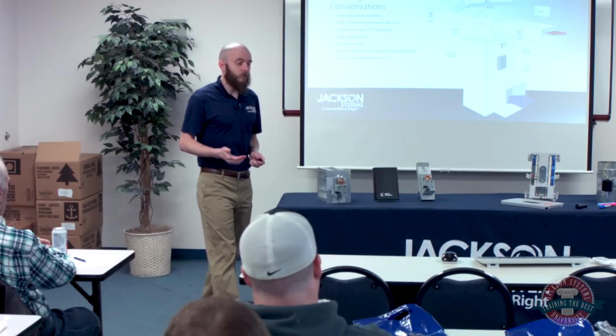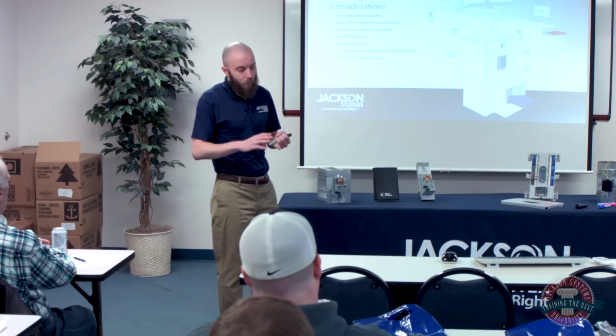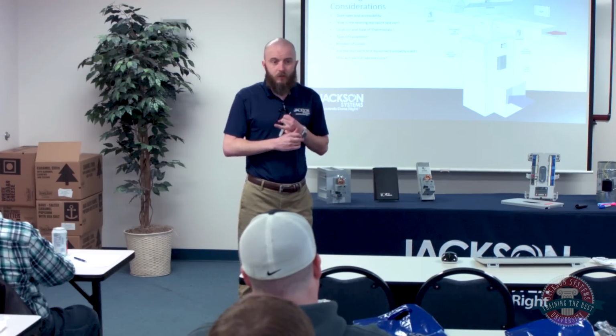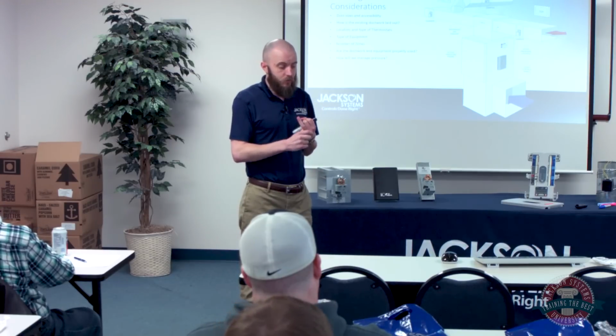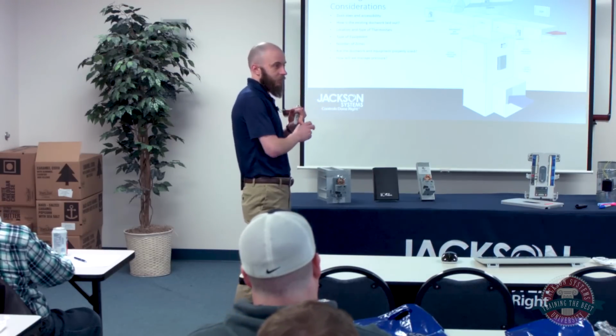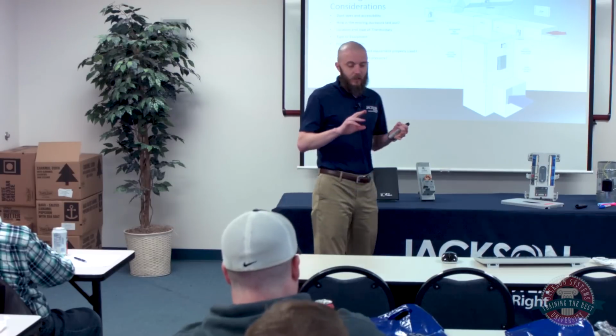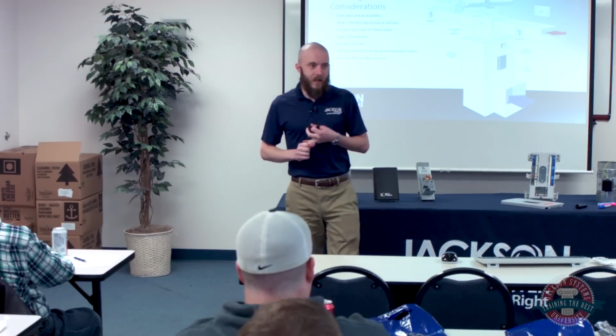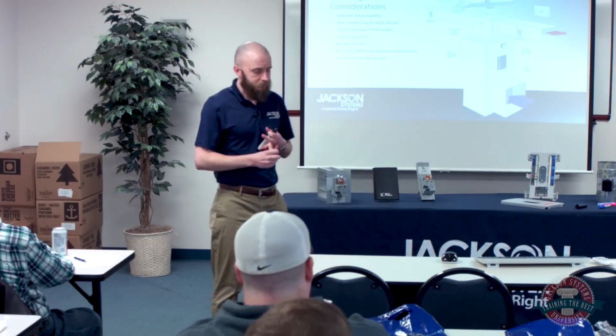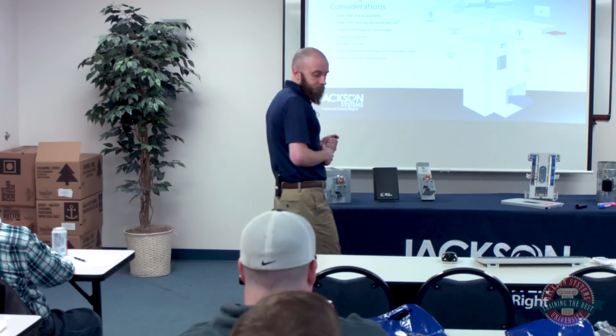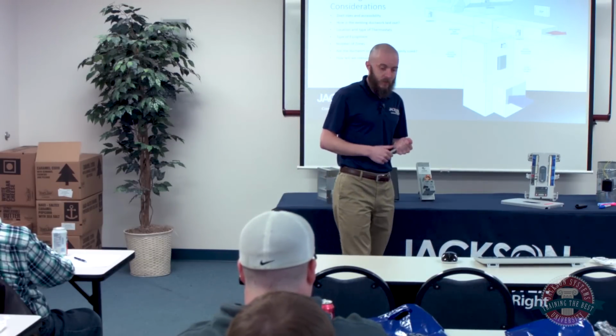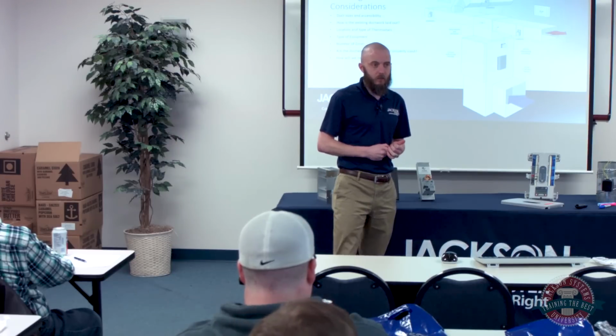Because if you don't, you're going to potentially end up with very noisy ductwork, which is a huge nuisance and is almost guaranteed to result in a callback. At the worst, you could damage or cause issues with the equipment. But static pressure is a big thing with zone panels.